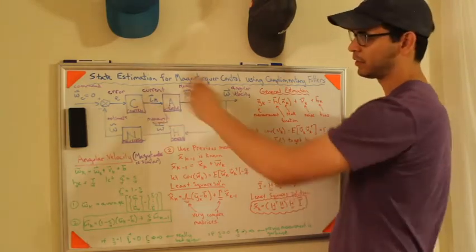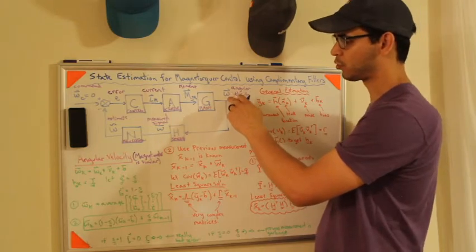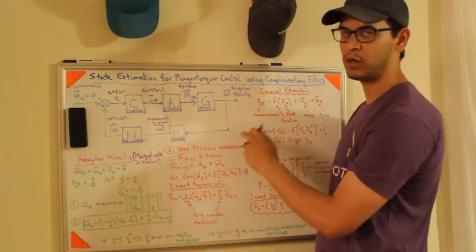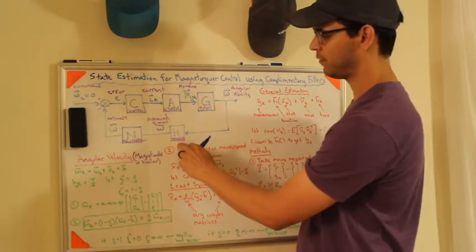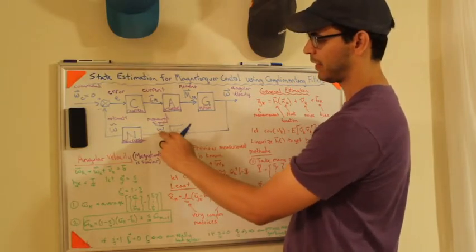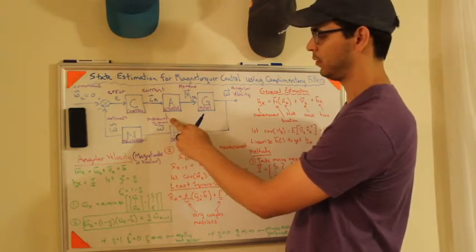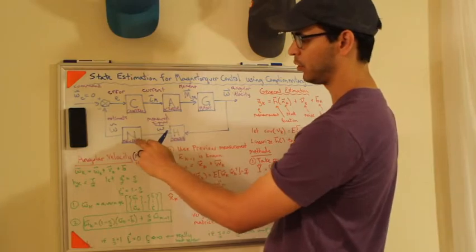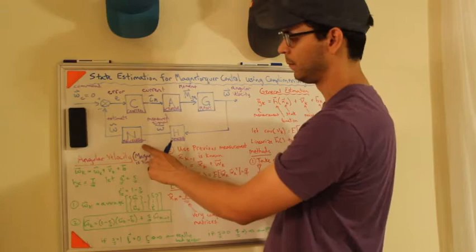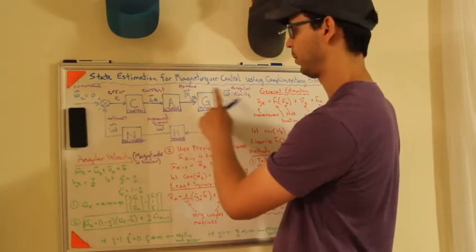This is the truth signal in this control block diagram. We assume that there is some true angular velocity that we can measure, but we don't directly know. If I have a sensor, and I'm going to call it H, I measure that signal, and that gives me omega bar, which is my measured signal. My measured signal then goes through my estimation block, which is my complementary filter in this case, but it could be something more complex. This is my navigation filter, which is going to give me my estimate of my truth.